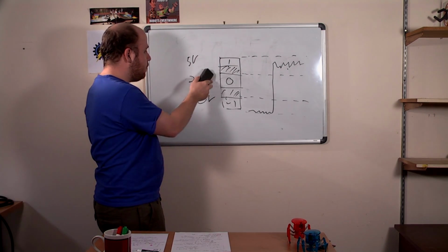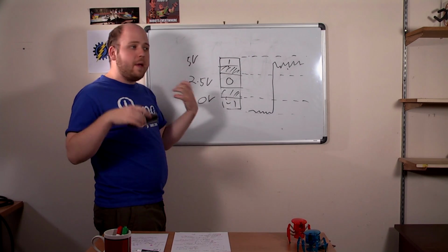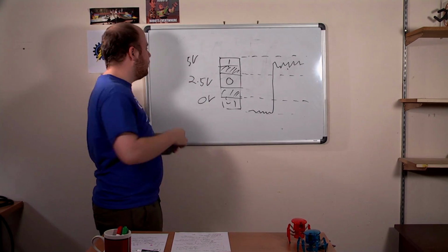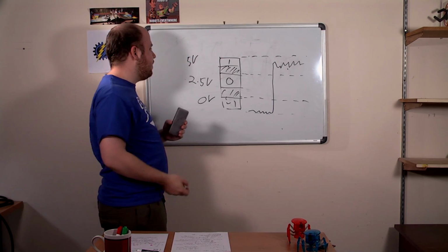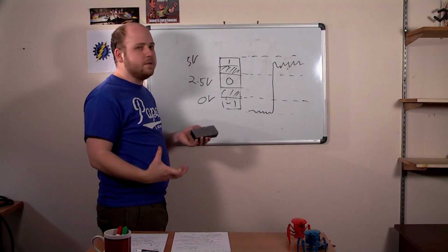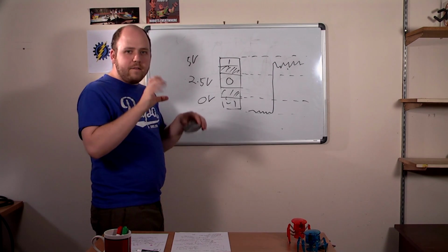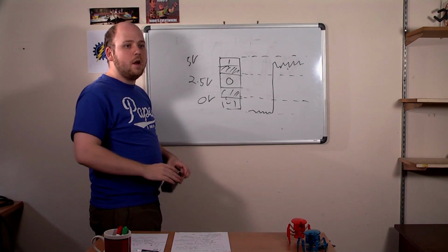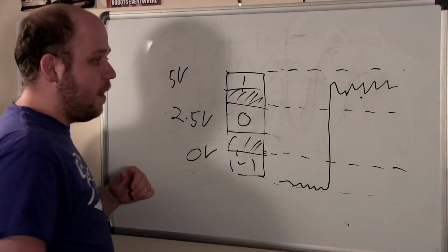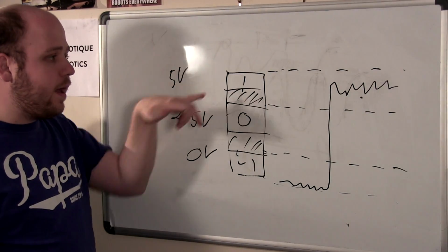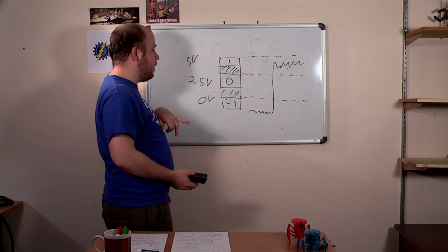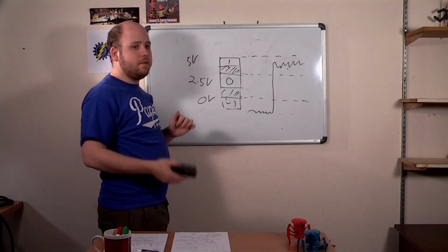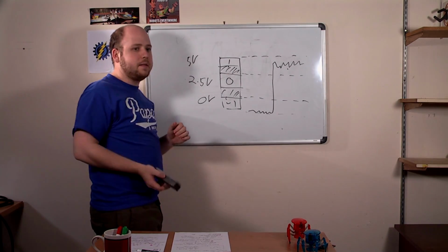So mostly what you will see when you're doing beginners digital circuit is actually 0 and 5 volts, 0 and 1, or sometimes instead of 5 volts, it will be 3.3 volts. But the idea is that you have single symbols, and it's pretty fine like that for most applications actually. So that's the first thing. You quantize the value, and that's for 1 bit. And then you can put streams of bits to represent one value from your analog signal.